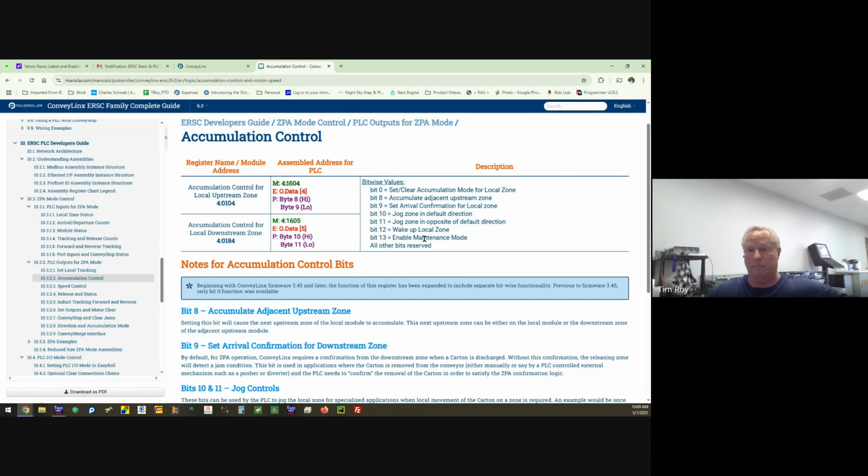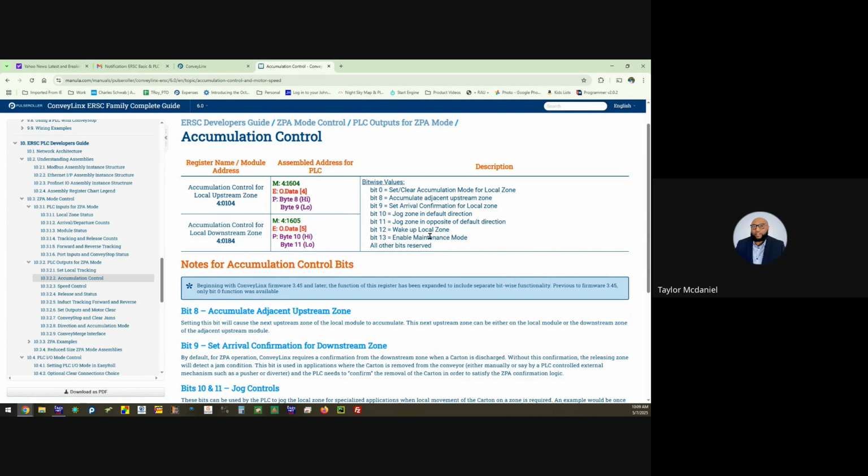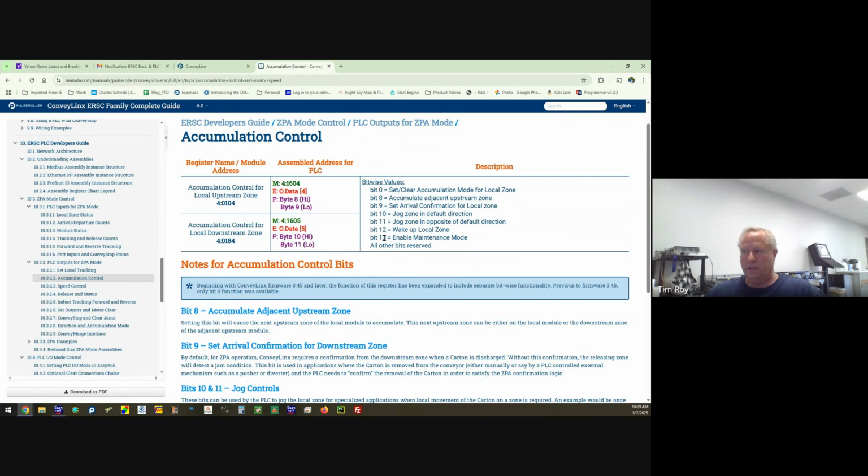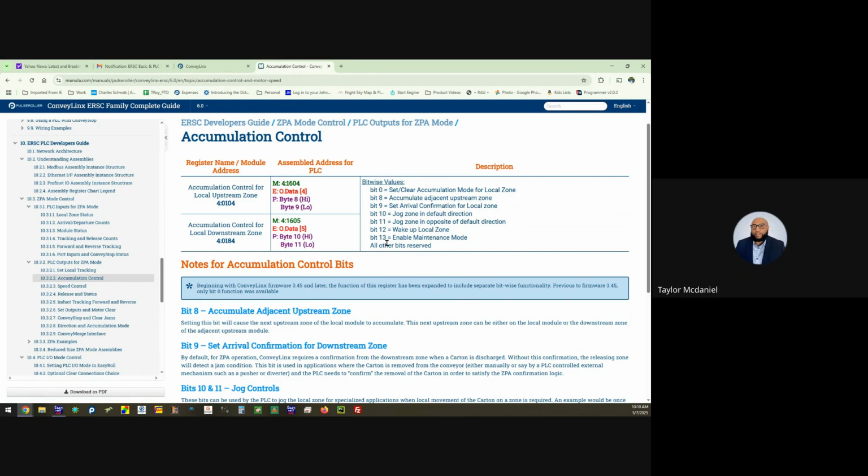A load comes from somebody else's equipment and blocks our eye, and the zone turns on to accept that load. You energized pin 4. Turning on bit 12 is the same thing, only instead of a hardwired photo eye, it would be a communications bit. No extra wiring involved. That zone just starts running, waking it up for a load.